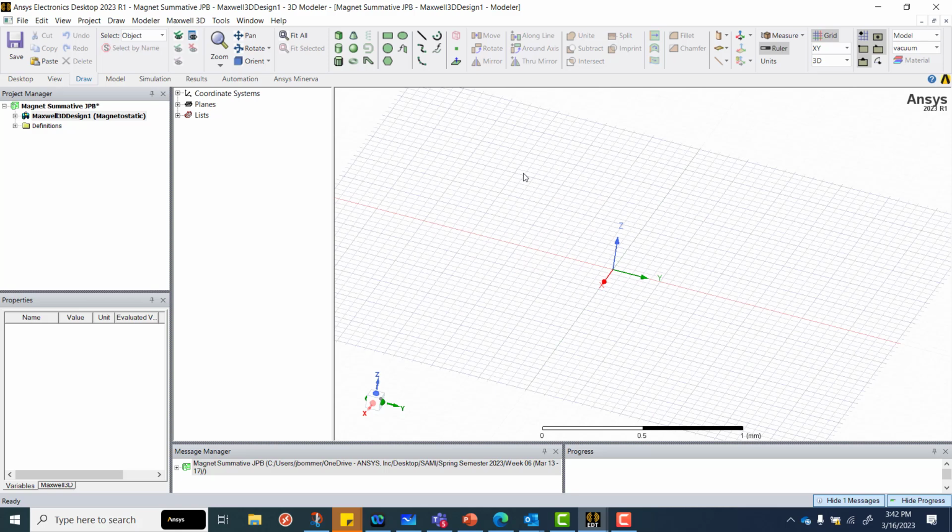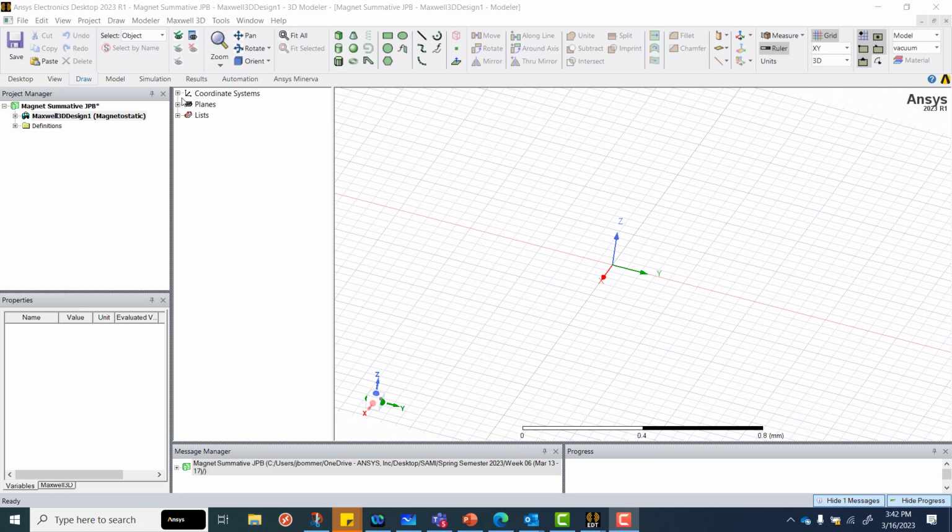So the first thing I actually want to do before I start creating geometry using some of these buttons up here is, even though I have an origin and my coordinate system is shown here, I want to create a number of local coordinate systems through the course of this project. So we talk about this a lot. We talk about the global coordinate system. If the W is shown, that means that's the working coordinate system. Any geometry that I create, or I should say translations or rotations that I apply, will be applied with respect to this coordinate system.